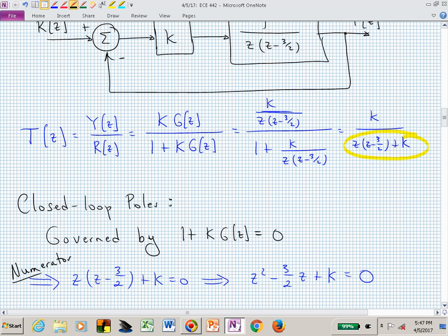We want to know now, I have a second-order polynomial. How do the roots of that equation change as I march k, or turn k, from 0 to infinity? That's what the root locus diagram is giving us. So if you have a calculator, if you have MATLAB, you could simply stay up all night and plug in different values of k, find the roots of that, and you would have your root locus in terms of numerical values, without memorizing all of these rules.